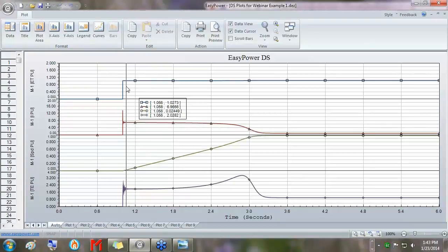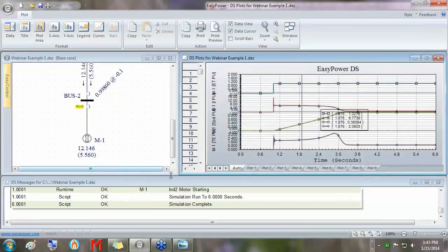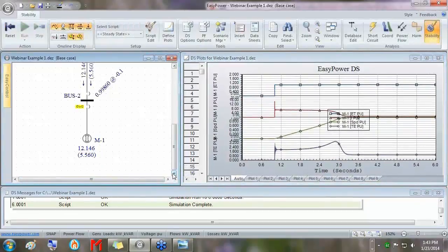Notice the interesting thing. Notice the voltage is 1027. It's a 460 volt motor on a 480 volt bus. And what you're plotting here is the motor voltage, not the bus voltage. You plot bus voltage, it'll show up at 1 per unit and then dip slightly. But here, we're seeing it on a 460 volt base. And that is true. If there was nothing on that bus before and this is a very light load, your voltage is going to be roughly 1 per unit, which is 480 volts, not 460. That's a nice little interesting thing to note.